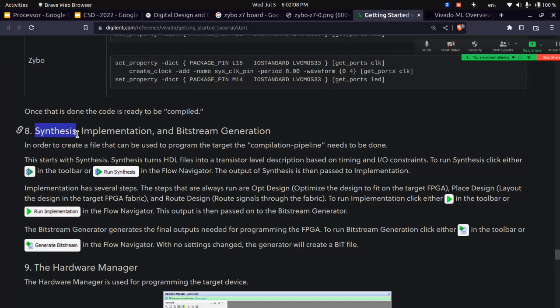Let me tell you about one design we did. It was working perfectly fine before synthesizing. As soon as you synthesize the design, there is optimization. Vivado will optimize your Verilog code to a format. It will remove unnecessary wires, unnecessary registers, and even components that you don't know about. If you look at the synthesized design, you will see many components removed, or wired differently and not working properly. It will try to change the meaning of the code itself.